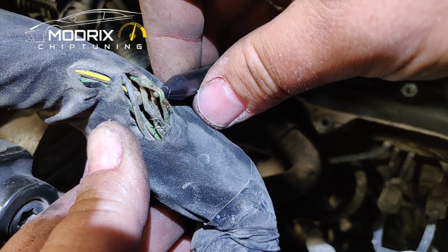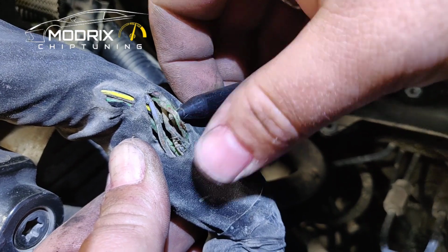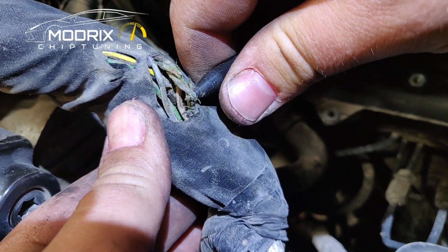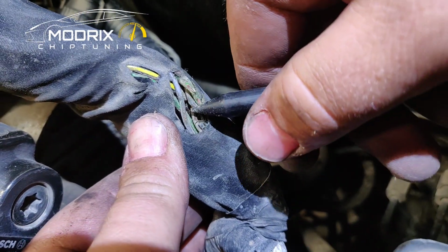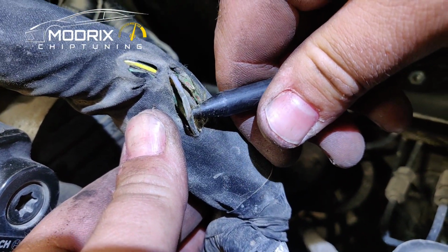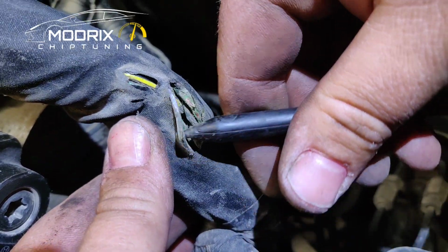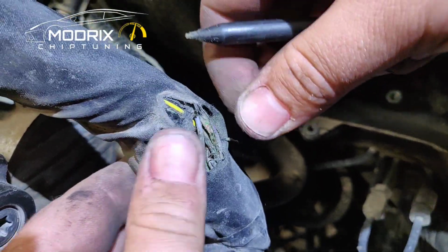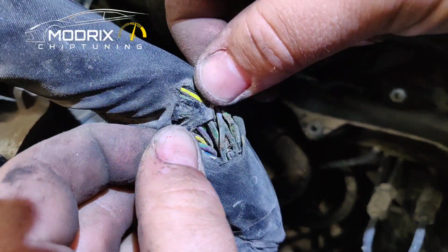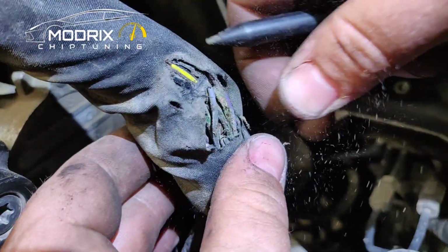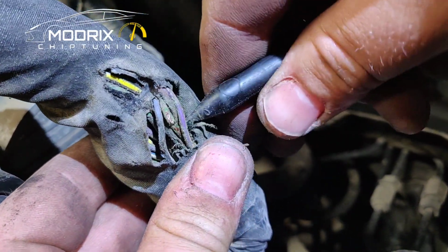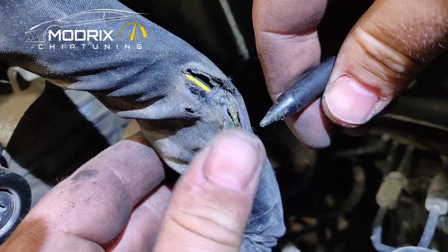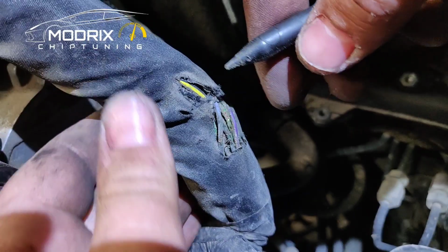It's split, so you don't have any contact. So this is the problem. Look, the next one is the same, and the next one is almost gone. I don't know for this wire which one it is. This is probably from different component, but only these ones. Look on this, it's been scratching probably from the factory. I'm not sure, but all others wires is okay. The deeper ones is fine. So the first ones was the first ones which one been smacked off.